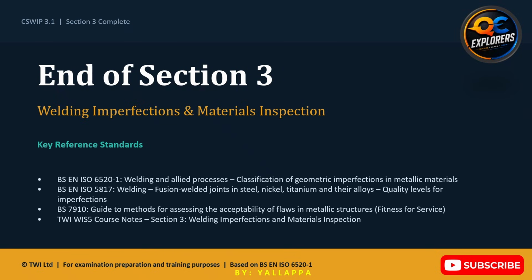The key standards identified in this presentation are BS EN ISO 6520-1, BS EN ISO 5817, and BS 7910, together with the TWI WIS 5 course material. As you prepare for the CSWIP 3.1 examination, try to approach every question from the perspective of a welding inspector. Ask yourself, what is the imperfection? How did it form? How would I detect or measure it? What is its significance? And finally, which acceptance standard applies? That is the professional inspection mindset.